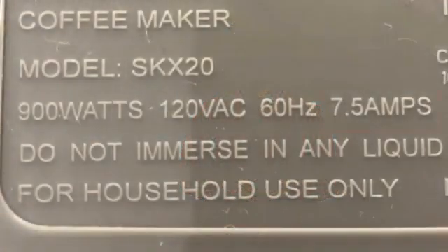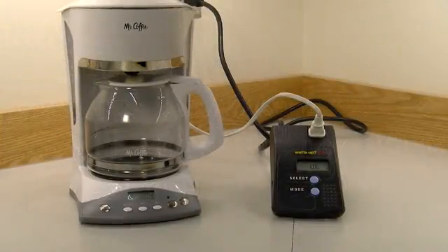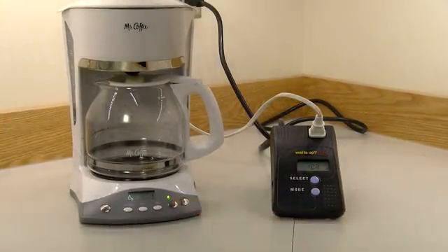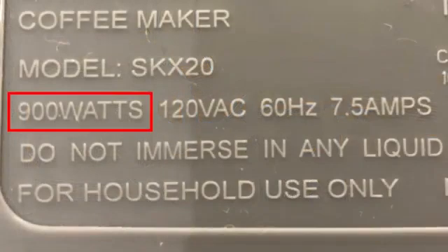A coffee maker is a typically high-powered device, and the label indicates that it consumes 7.5 amps when in use, plugged into our watt meter. So we can see that the background power is about 0.5 watts, but as soon as we turn on the power, it goes up to 873 watts. 120 volt operating system voltage times 7.5 amperes equals 900 watts. So the coffee pot is operating near its maximum rating.